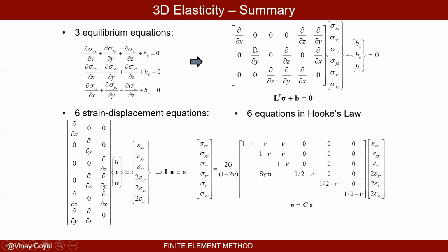So you can see that this arrangement of this matrix is actually quite convenient because I'm able to write these 3 equations in matrix format, which is extremely convenient in finite elements. The second equation works in a very similar way. You can see how this gets multiplied by sigma yy, and that's that term right here. The derivative with respect to x times the last one is that very first term there. You can see that it turns out very nicely. That second row times that stress vector gives you that second equation. That third equation the same way, I can take that row times that stress vector and get that third equation.